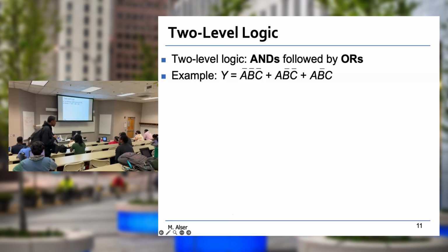Any question about how we draw it? Yes, please. Is it better to just have it all as one input instead of breaking the A into 3 separate lines? Oh, I see. Normally you have this as a single switch. If you add it as 3 A's, then that's 3 switches, and you might mistakenly enable one of them, leaving the other untouched. Then you're not having A, you're having something else. If you guarantee that all of them will be the same value, then yes, you could split them.